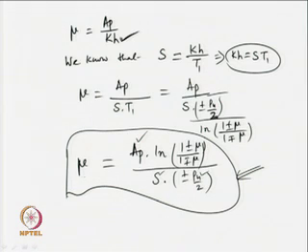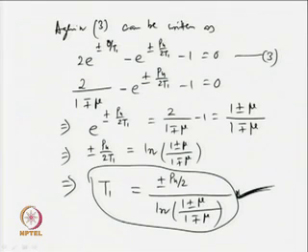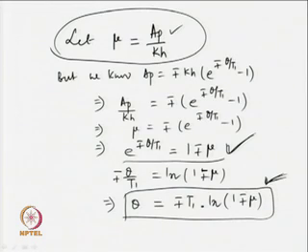Then this expression can easily be solved to find out mu. And once the mu value has been found, then substitution of mu and making use of the measurement pu, we can estimate T1. Further, making use of T1 and mu will give us theta. That is how all the unknowns of the transfer function model can be estimated.